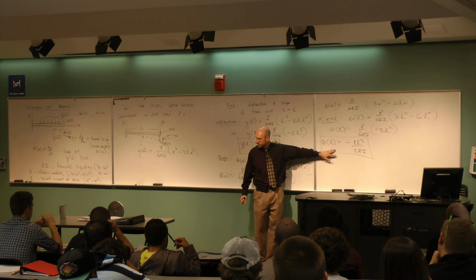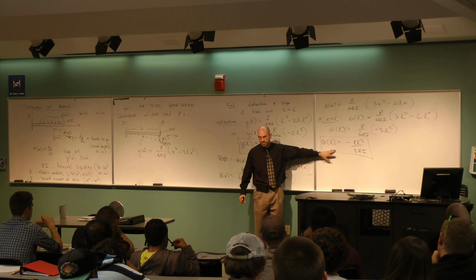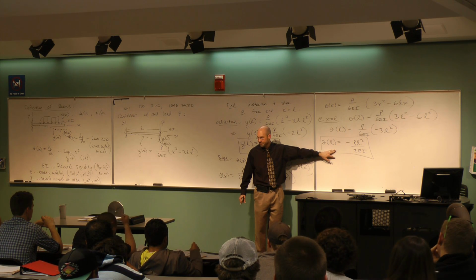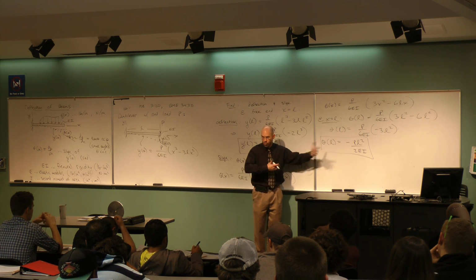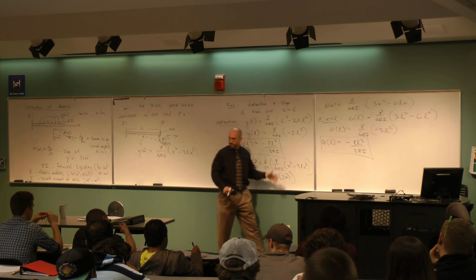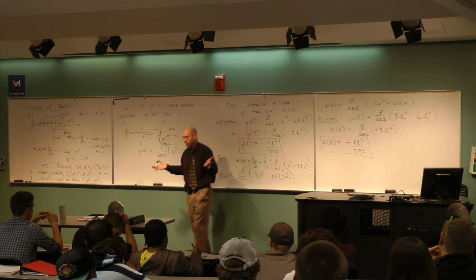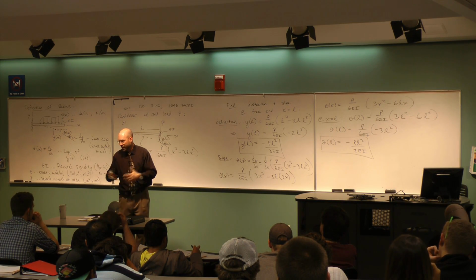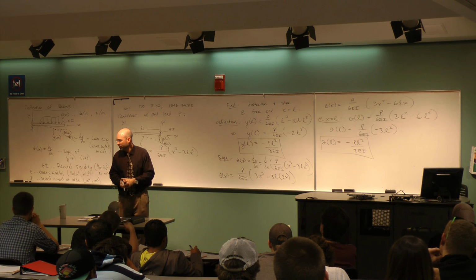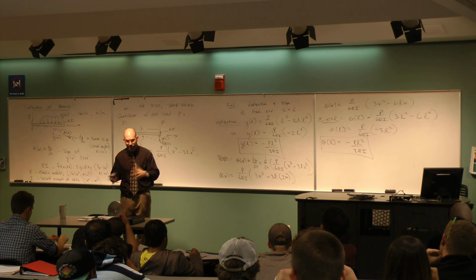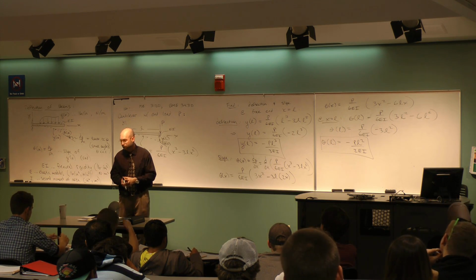What about the slope? Replace the E with 3E and get what? It's still 1/3, right? So the slope's not always more sensitive to a design change than the deflection. If I change the length, I get way more effect on deflection than I do slope. If I change the material, I get the same effect. This is why we do problems with letters, so we can get a sense for how I can change the design. I'm the engineer, and so I can get it to do what I want for whatever parameter I'm interested in by adjusting how I design the beam.